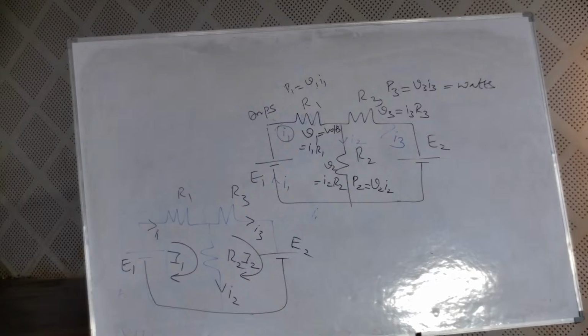Mesh method we have to apply. What is the first one? The number of meshes. How many meshes are there? Two. Condition: both clockwise or both anti-clockwise, take any. Then apply the procedure and we'll get the answers I1, I2. I will tell you the procedure later, by taking one problem. Then you automatically get the branch currents. Is it clear? Next. Mesh is completed.